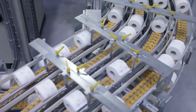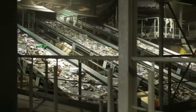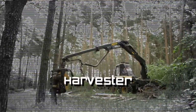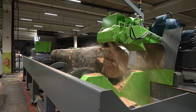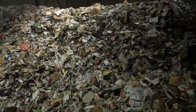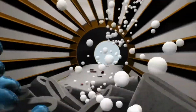The production of paper obviously begins with securing the key raw materials: wood pulp from trees and recycled fiber from used paper products. Trees like spruce and pine are harvested from forests and transported to the paper mill facility. Debarking the trees is accomplished using a machine called a ring barker that scrapes bark off using various blades at extreme pressures. Here they undergo debarking to remove bark before getting chipped into small pieces to start breaking down the wood. Paper materials collected for recycling, including cardboard, newspapers, and office paper, are repulped mechanically using water and pulping actions which return the paper to separable fibers.